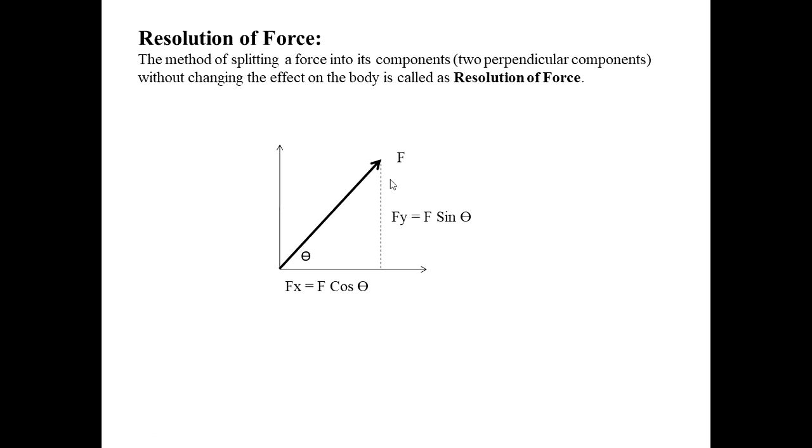Now, this is a force F at an angle of theta. I want to resolve this force into two perpendicular components, that is Fx and Fy. This theta is with respect to x. So the Fx component will be F cos theta and the Fy component will be F sin theta. This is by using simple trigonometry.